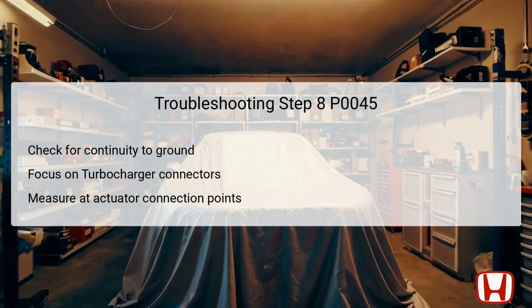If there is no continuity, this suggests that the actuator internal circuit is functioning correctly. In such a case, you may want to check additional service information or consider substituting a known good PCM as a step forward in troubleshooting.